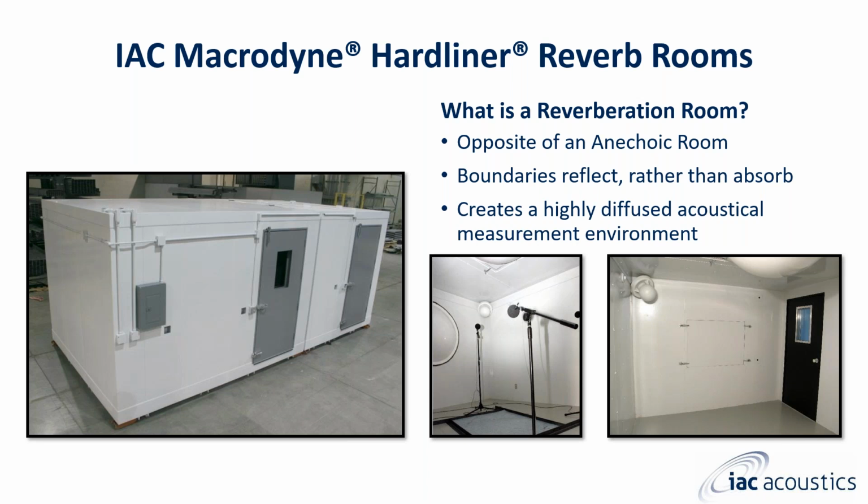To obtain good diffusion with any room configuration, stationary diffusers and/or moving vanes may be needed to provide an interchange of sound energy for uniform distribution of room resonances. The general concern for a quieter environment at home, in the office, in plants and schools and hospitals, inside and outside motor vehicles, has resulted in a large number of rating standards, criteria, and government regulations for the control of noise. These have been developed for several industries by institutions such as ASTM, ANSI, ASHRAE, IEEE, ISO, and others, most preceding the current concern with noise pollution.